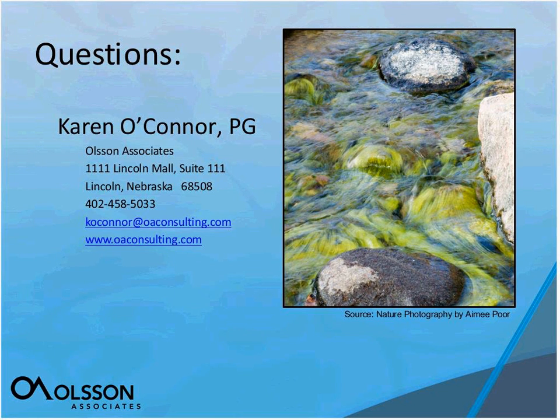The first one is, why is the drawdown so symmetrical? So that has to do with the aquifer itself. This is a fairly homogeneous aquifer. In areas where the aquifers are discontinuous, you would see a change in the shape of that drawdown. But when you do pump from a well, there's going to be what they call a cone of depression, and it is a circle. It's symmetrical. Unless there are geologic factors that are going to make it change and discontinuous in certain areas.